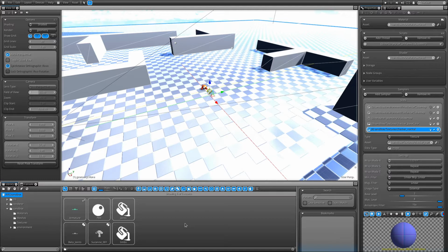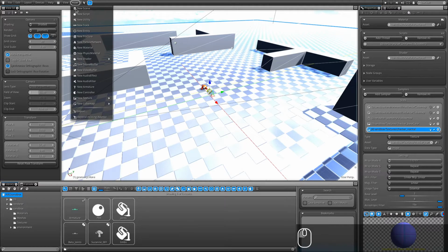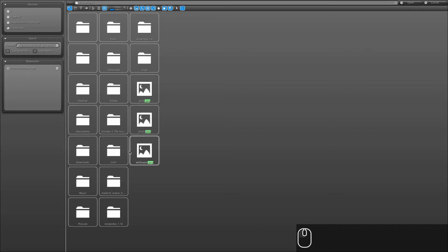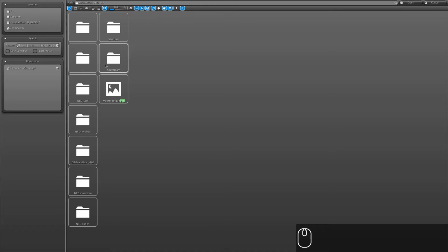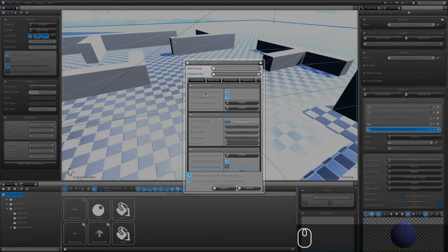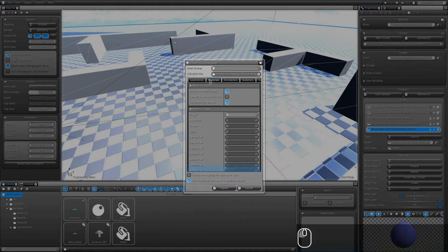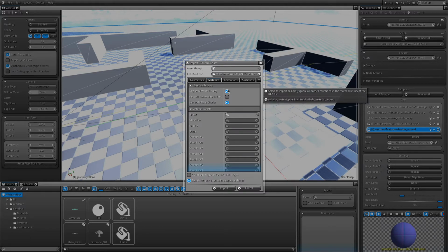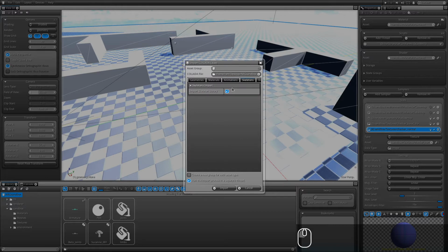So we are going to go under library, asset, and import, and we are going to search for our tank.dae. Open up, and I'm going to import the geometry as it is. I'm going to toggle that off to ensure that all the assets will be placed at my root here. Material, this time I am going to import the material because I'm going to create a custom preset for that specific material. Animation, I do not have animation on this one.